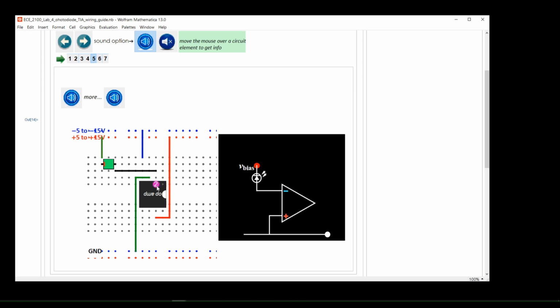The photodiode illustrated is only representative, it is top-looking. The actual one you have might be of a different type, such as side-looking, and appears different. Follow the instruction about the position of cathode and anode next. This is called reverse bias, that is, the cathode voltage is higher than that of the anode. It is opposite to the LED. A photodiode is always used in reverse bias, it should never be forward biased like a LED.